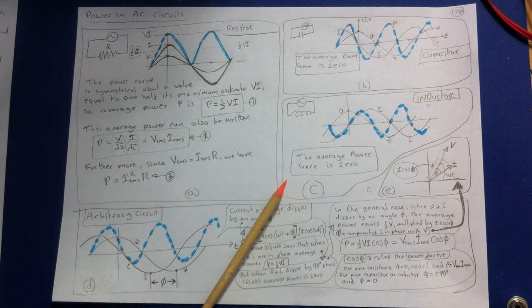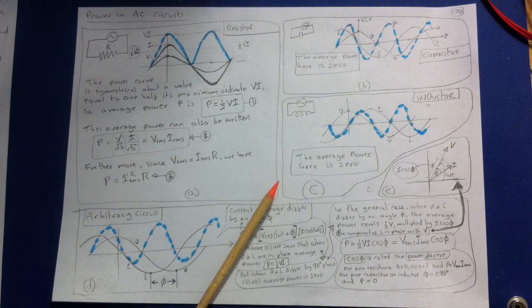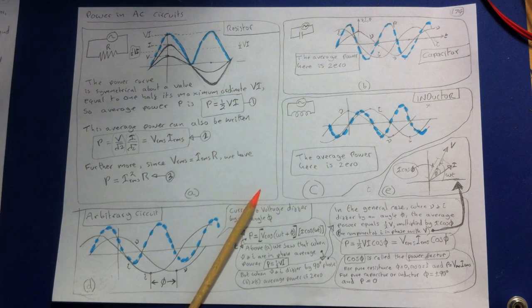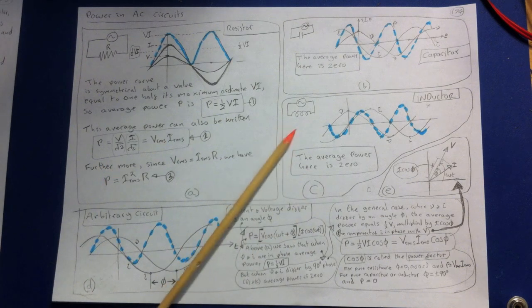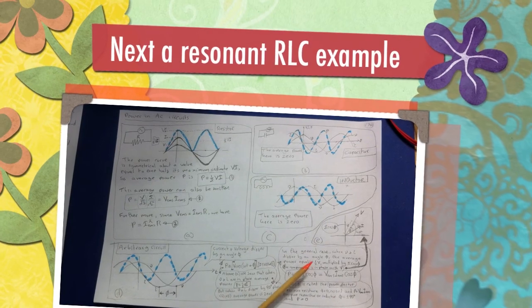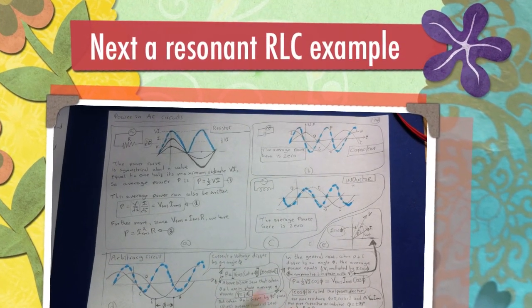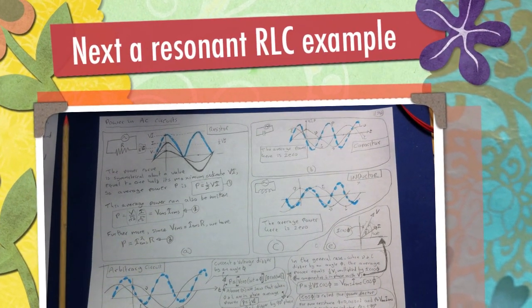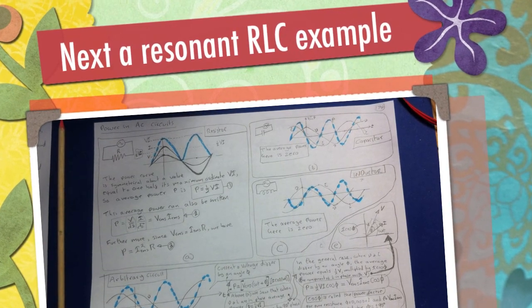Many types of AC machinery draw a lagging current. The power factor can be corrected by connecting a capacitor in parallel with the load. The leading current drawn by the capacitor compensates for the lagging current in the other branch of the circuit. The capacitor itself takes no net power from the line. If we put a capacitor in line, it will balance out this angle. We don't get this waste of heat through the transmission lines. So that's a very quick intro to power in AC circuits.